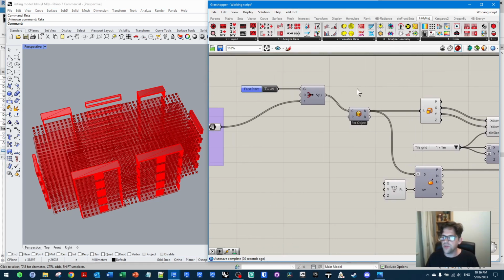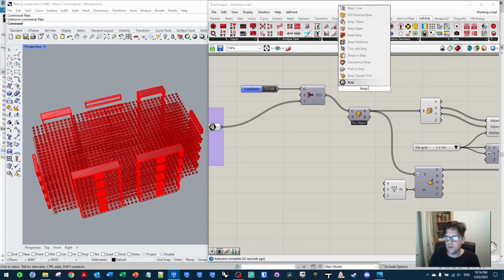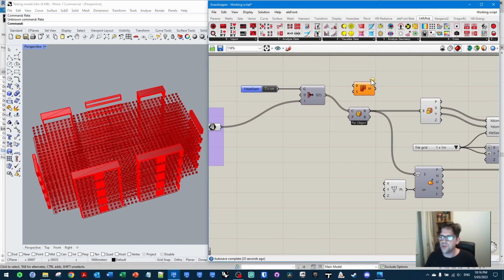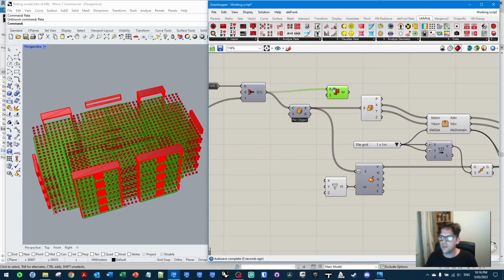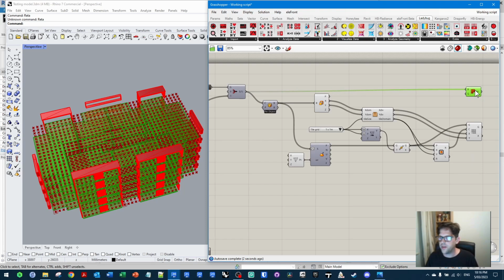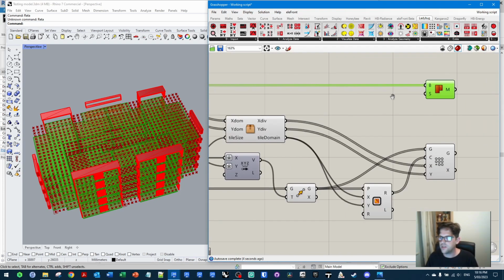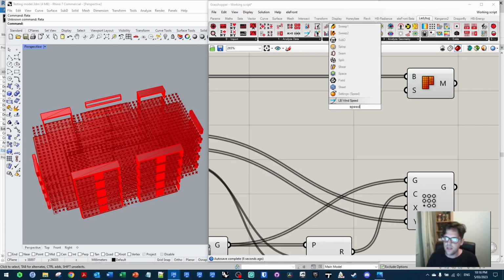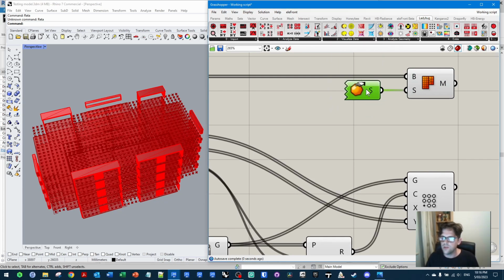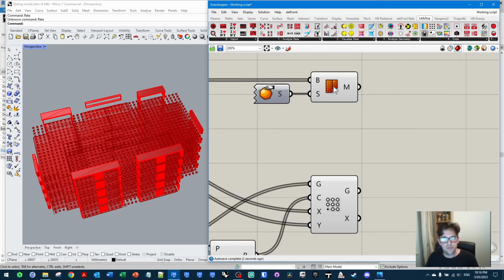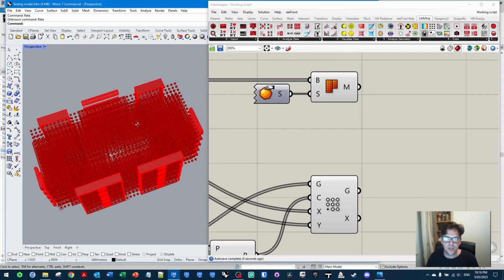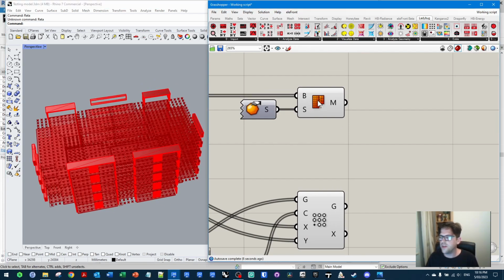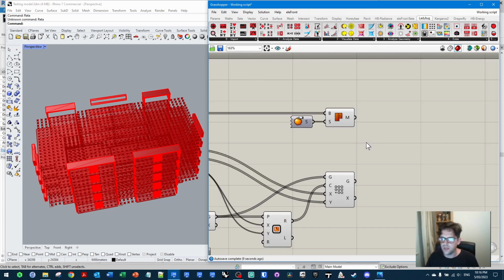So I'm going to take my original apartment surfaces and turn them into a mesh using BREP mesh, which is a little bit quicker than using straight to mesh from what I've found. In this case, we can use the speed settings to just target the fastest version of turning this into a mesh. Now, at the moment, those meshes are pretty messy, but we only need them to be intersected with effectively.